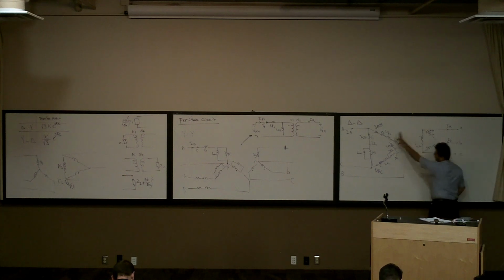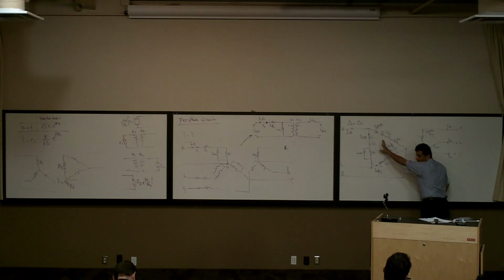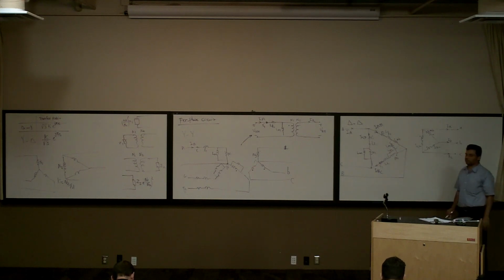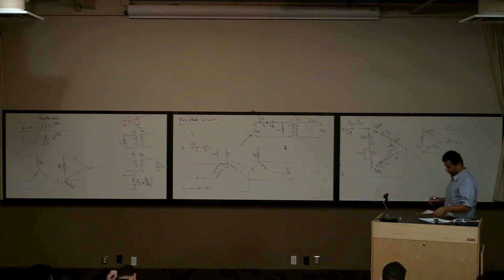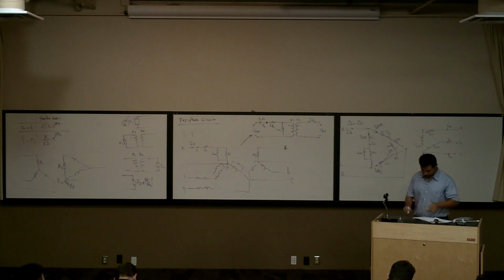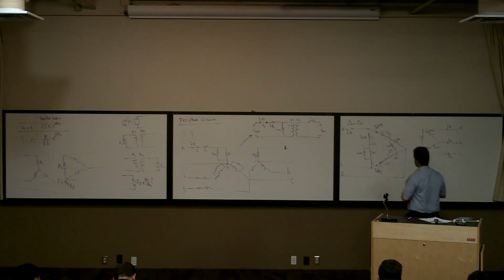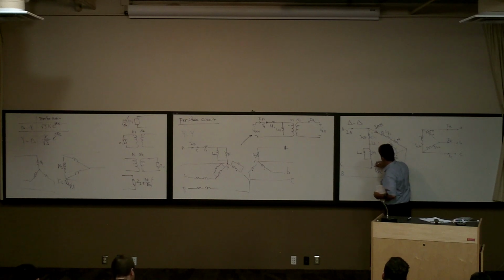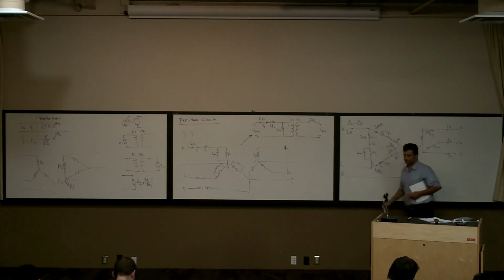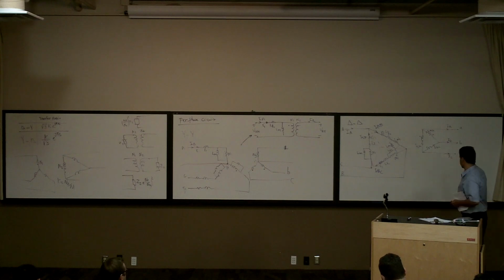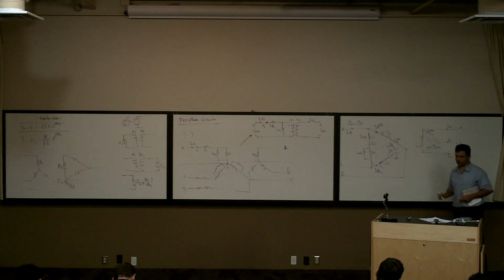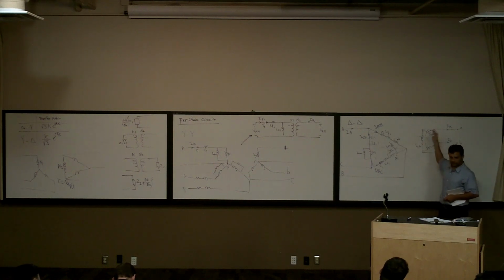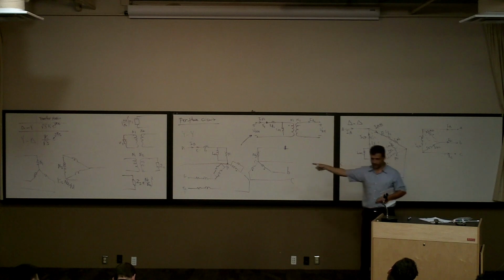I transfer all the impedances to the primary, okay? All the impedances, I draw them in the primary. Now we want to see what's the per phase circuit. What does per phase mean again here? If I'm going to go per phase, it is like I come up with a kind of equivalent circuit here, right? I'll convert this one to a star, and this one to the star, so basically it becomes like that, right?